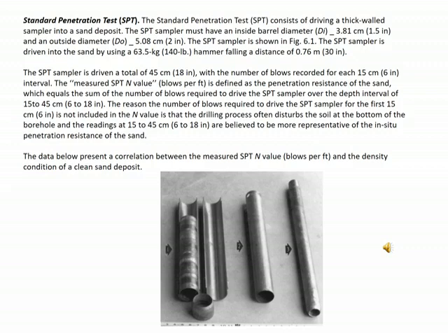As defined by penetration resistance. So we drive, and for every drive, how much it goes through the sand has to be measured. So this blows per foot has to be measured. So this is the standard penetration test, the SPT test.